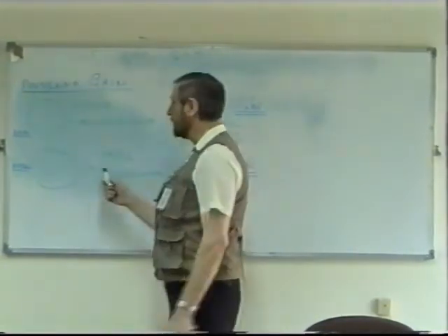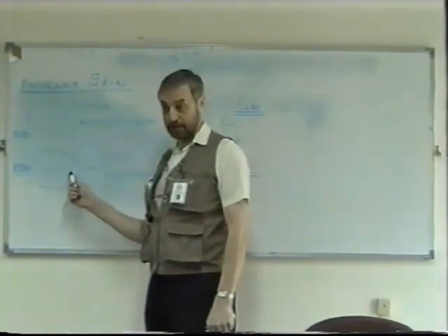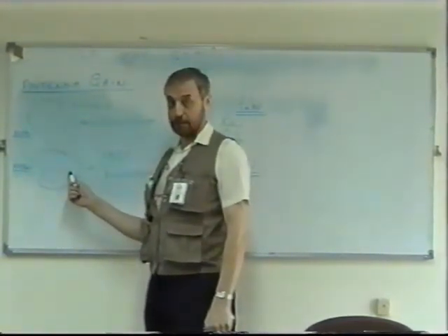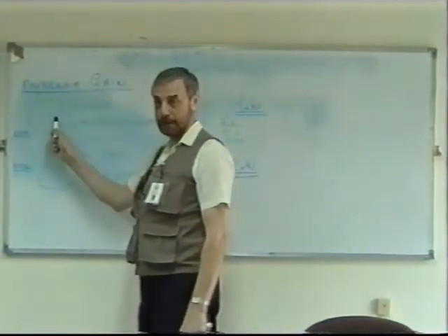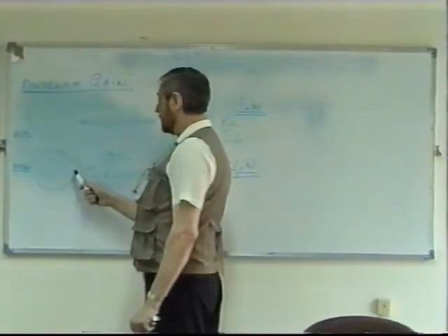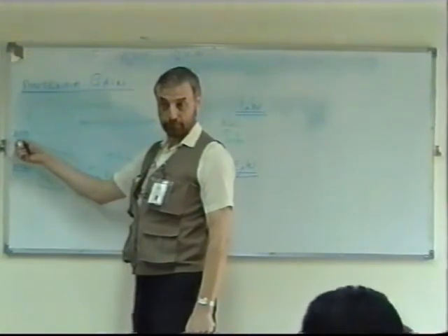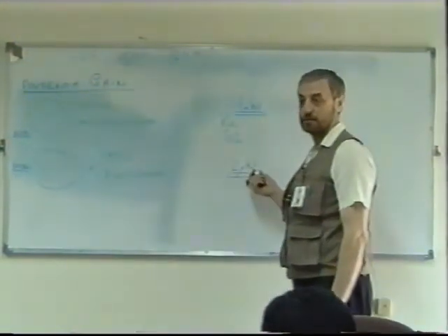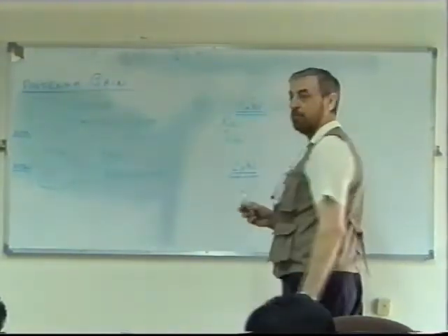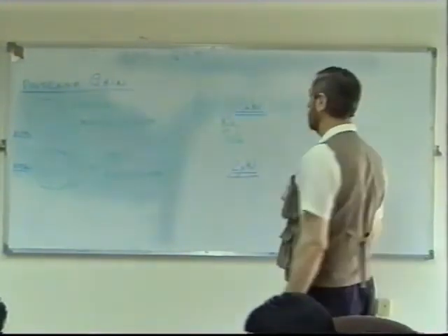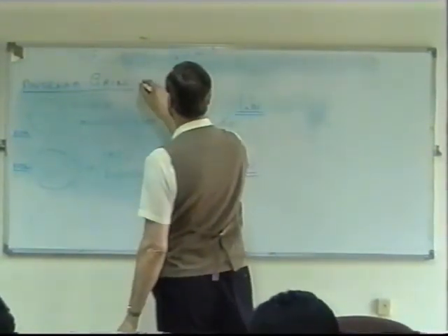No, the antenna gain depends on the shape of your polar diagram. In other words, it depends on the type of antenna. Right? So if I was to use a Yagi instead of an omnidirectional, it's exactly the same thing as using an omnidirectional at a bigger power as far as the received signal is concerned. So we call that antenna gain. So technically it's a ratio of powers. Okay? I'll put down here the definition of what antenna gain is. Here's the definition.